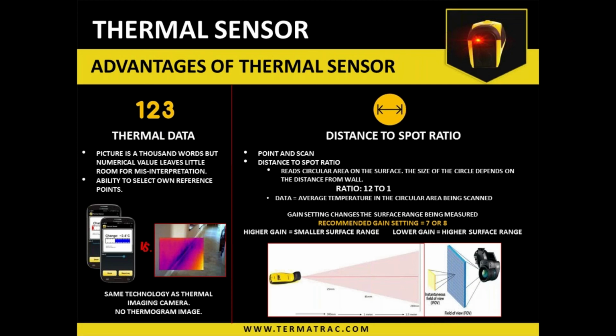So having to move parallel, vertically, horizontally, diagonally, it does not matter, but we must remain at the same distance that we were when we referenced it. Now that is no different to a thermal image camera. They're designed to be worked in the same manner. Must be used parallel, and each camera has its own specification as to the optimum distance to be used from the wall. It'll also indicate the specifications of cameras on how fast we should be moving as well.